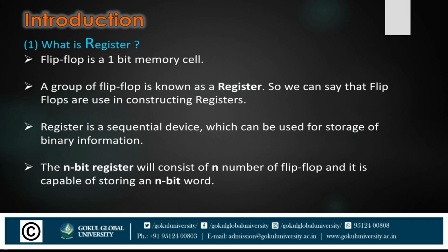First of all, what is a register? A flip-flop is a 1-bit memory cell and a group of flip-flops is known as a register. So we can say that flip-flops are used in constructing a register. A register is a sequential device which can be used for storage of binary information. An n-bit register consists of n flip-flops and is capable of storing an n-bit word.